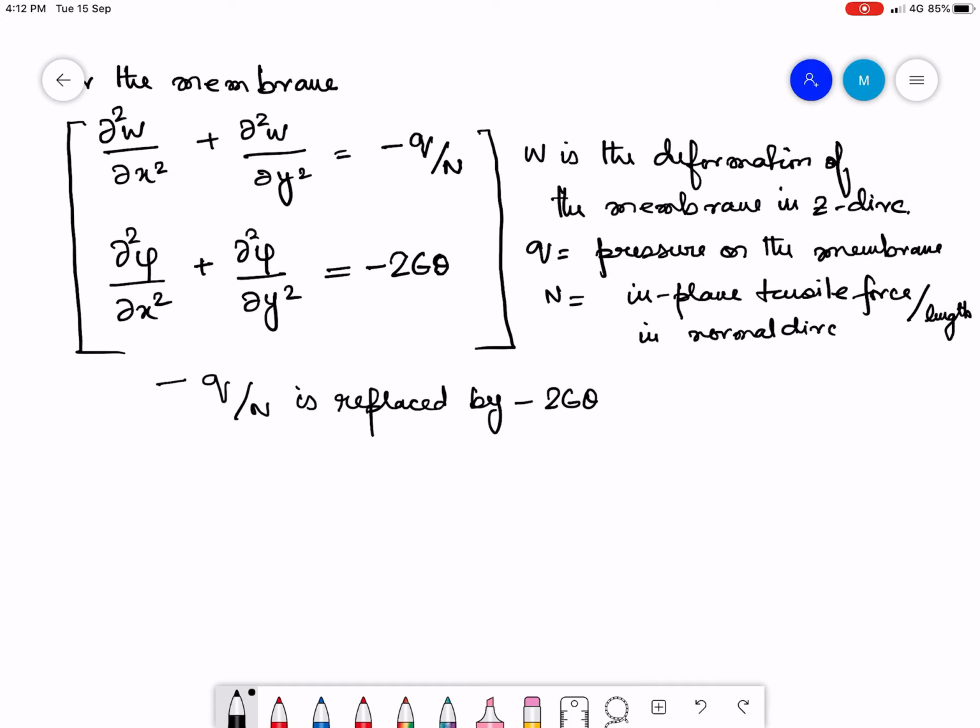Now, we all appreciate that once we get hold of the stress function, then we can solve the torsion problem with much ease. The only problem lies in getting hold of a stress function. So, once the stress function is obtained, our life is very easy. We can do any analysis of the shaft once we get hold of the stress function.